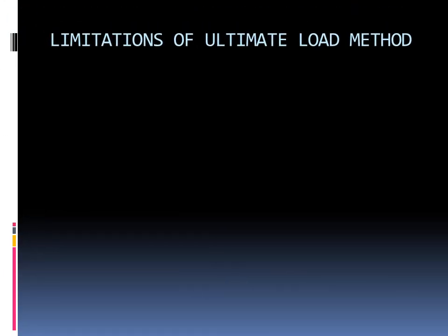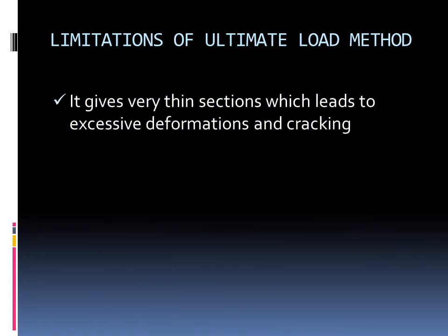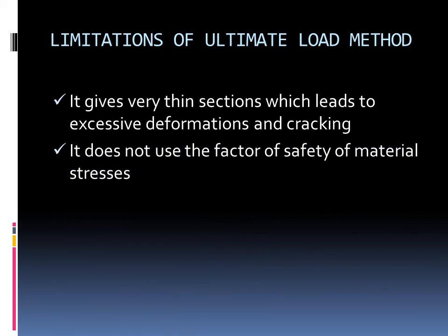Now, next are the limitations of ultimate load method. It gives very thin sections which lead to excessive deformations and cracking. It does not use a factor of safety on material stresses.